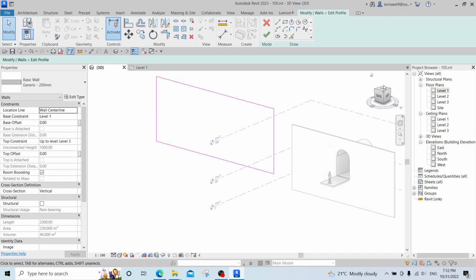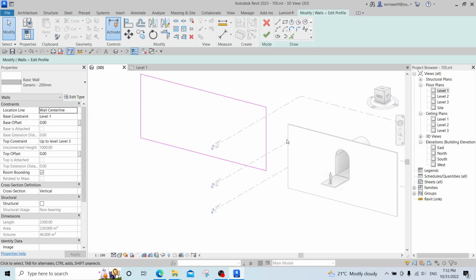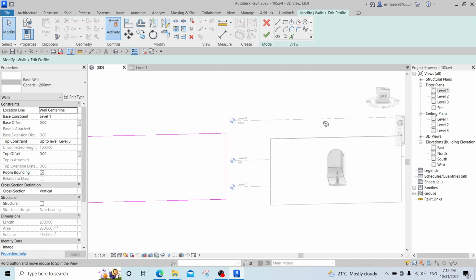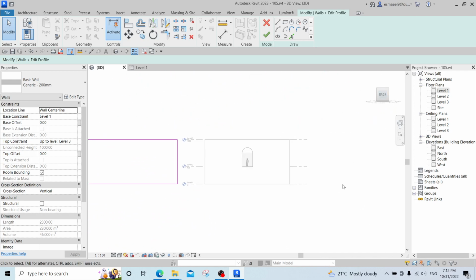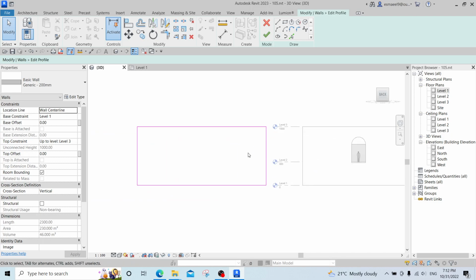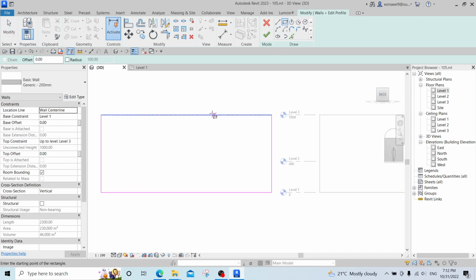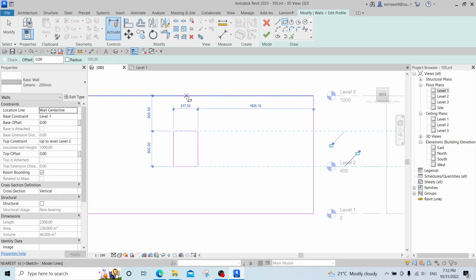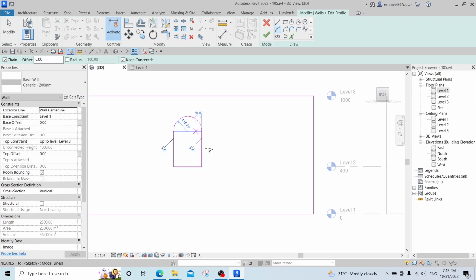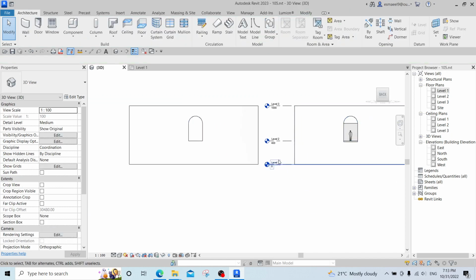And from this little cube in here, you see when I'm rotating, it's rotating with me. Let me just click on back one time. Now, I'm just standing as, or just seeing, I can see the model as elevation. We draw a rectangle like this, and it was 250 by 300 by 300. We choose start and radius arc, and then we click 1 point, 2 point, and then click this one and delete the last one and say yes. Now we do have this opening.